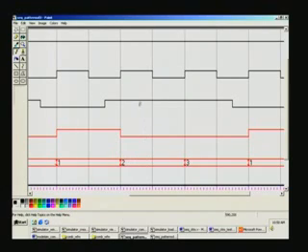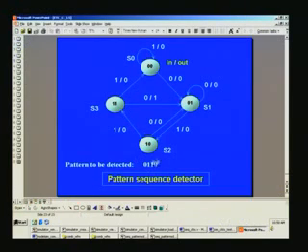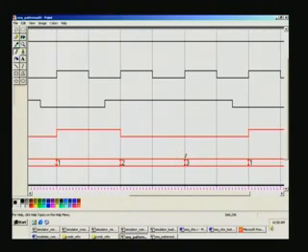And in state 2 we are analyzing, isn't it? So in state 2, what we sense here is 1, and it goes to S3. Is it correct? It's going to S3, and just keep track of the pattern that we have already encountered: 0 1 1 0. Now 1 has come. So again you see two 1s are there. So even the last pattern also is taken into account. So 0 1 1 again. Once again you see a 0 here. So promptly the output goes high here, right?